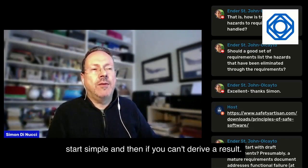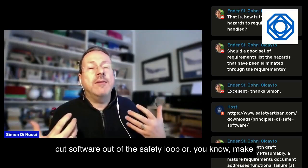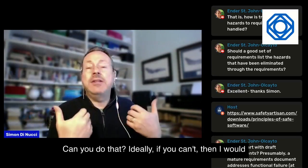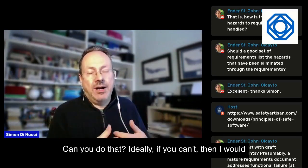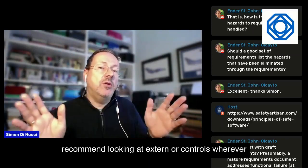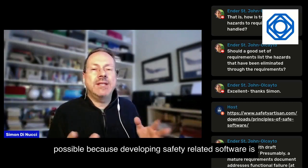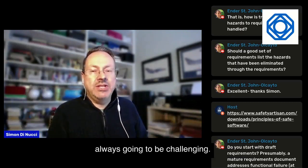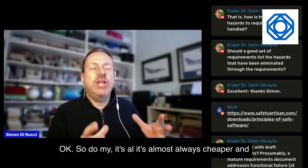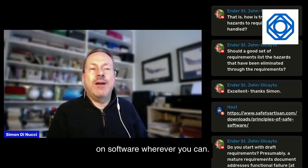But if you're starting from scratch, my advice would be start simple. Think about whether you can cut software out of the safety loop, or make the software completely non-hazardous. Can you do that, ideally? If you can't, then I would recommend looking at external controls wherever possible, because developing safety related software is always going to be challenging. It's almost always cheaper and better to reduce the reliance on software wherever you can.